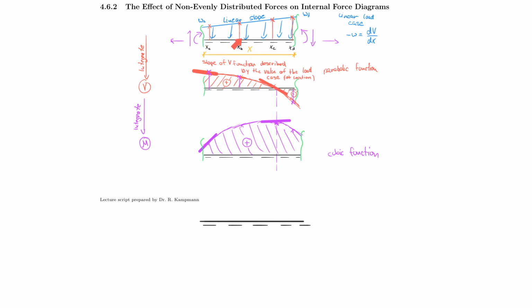So when this beam here starts to smile, it actually produces a curvature of the smile, right? It can smile a lot or only a little bit. And so it turns out that if you actually integrate the moment, you can define the curvature. The way that engineers do that is really by this angle here. So let's call that theta, the angle to the horizontal direction. And so if you integrate your moment, you actually find the angle, and you can do that at every location, right? Just like we did it for every part along the axis for the moment and for the shear force. So you can find the angle that the beam has at a certain location.